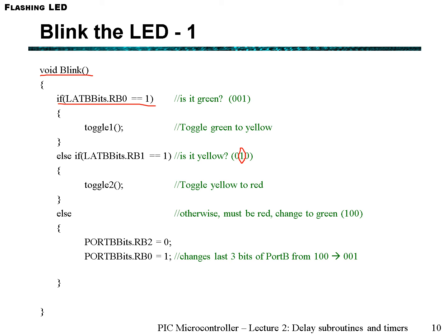So have a look at what we do here. We're setting the output of bit 2 to be 0. So that's the 1 in your state. And then we're setting bit 0 to be 1. So in this case, we're switching off the red LED and we're switching on the green LED. And then at the end of it, we would have a 500 millisecond delay. So let's just represent that 500 millisecond delay as a function called delay 500 millisecond.